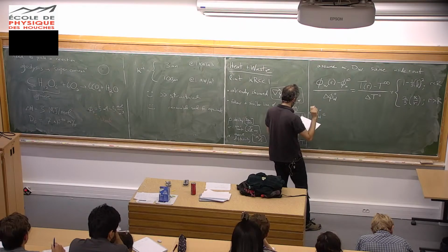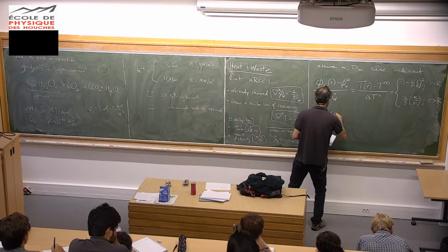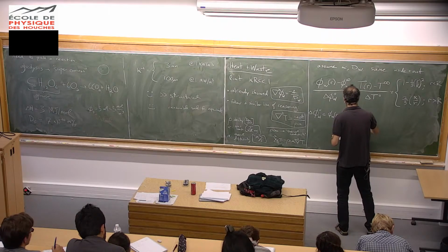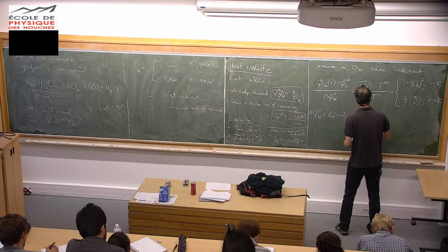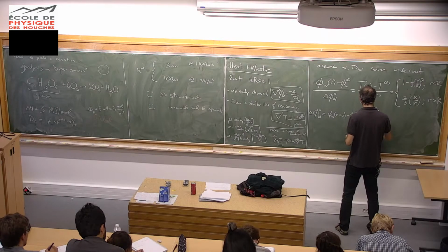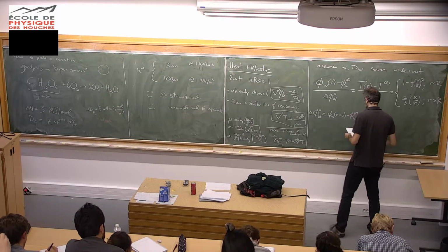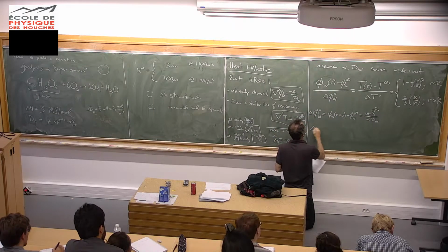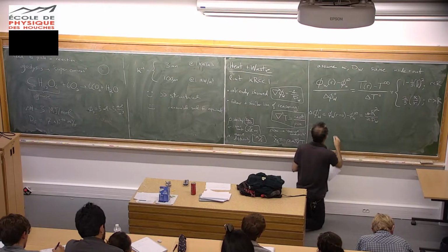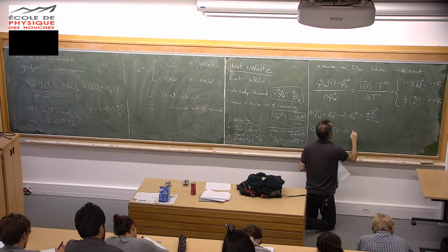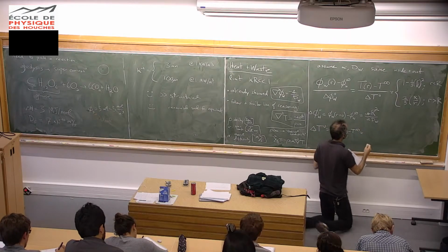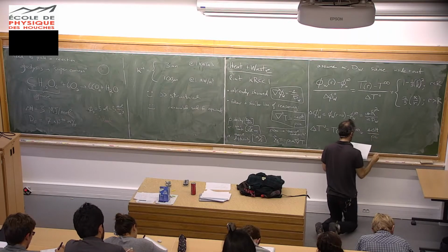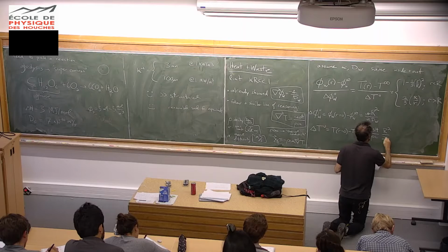So this is what I call, it'll become obvious in a second, the excess at the center. So it's phi w at r equals 0 compared to phi w at infinity. And that's proportional to the reaction rate times R squared divided by twice the diffusion coefficient of the waste. Similarly, the excess temperature at the center is T at r equals 0 minus T at infinity. And similarly, that is proportional to S times delta H over rho C, and then R squared over 2 alpha.